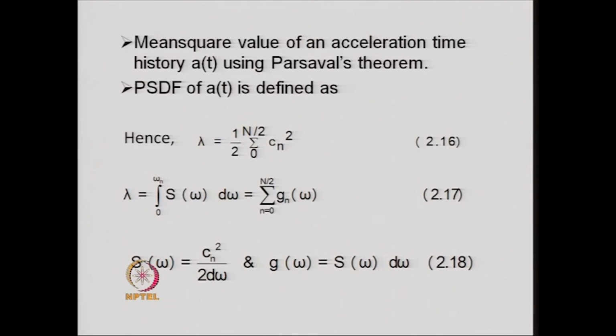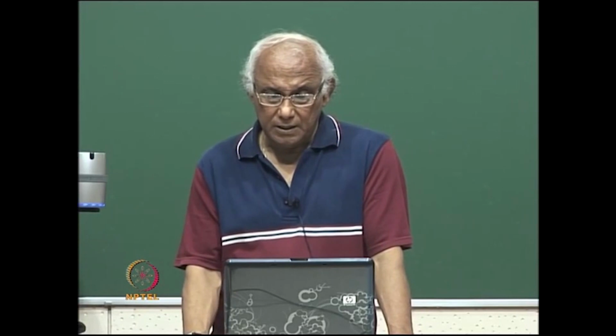Now, instead of the Fourier series analysis, if we carry out the FFT analysis, then from the FFT we get the amplitude at different frequencies, that is what we had shown before, and those amplitude squares are taken from 0 frequency to N by 2, that is the first N by 2 plus 1 values of the FFT that we consider to obtain the value of the Cn square.